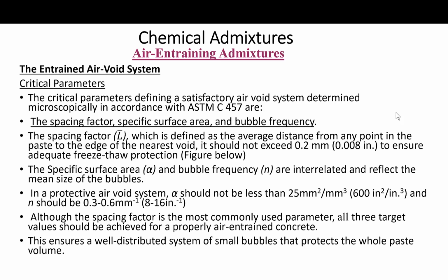Although the spacing factor is the most commonly used parameter, all three target values should be achieved for a properly entrained concrete. All three values, so that this will ensure a well-distributed system of small bubbles that protects the whole paste volume. These values are attained when the recommended air contents